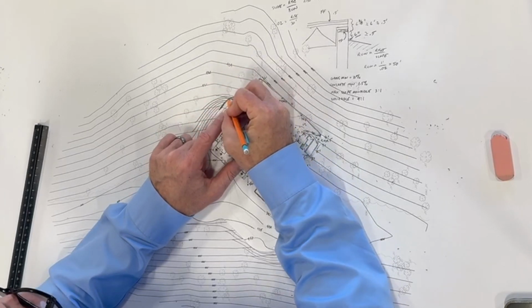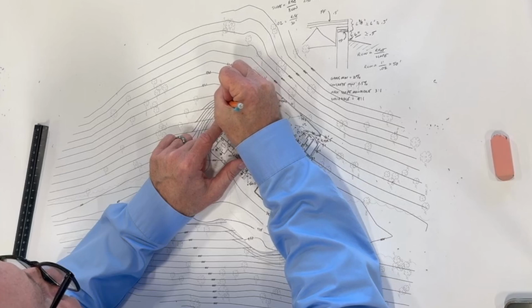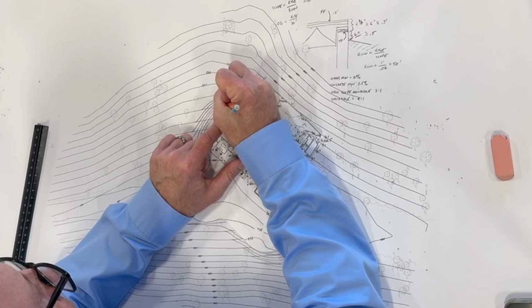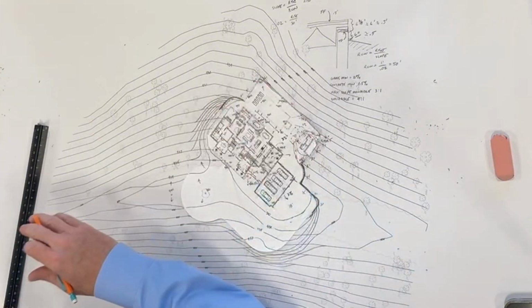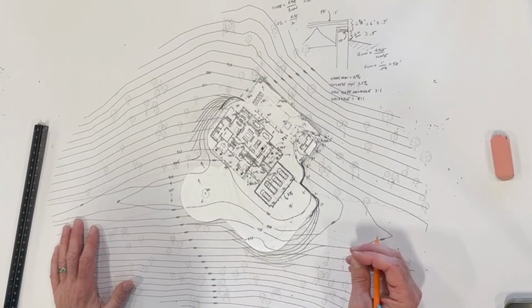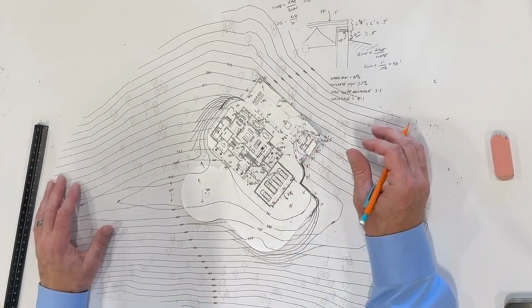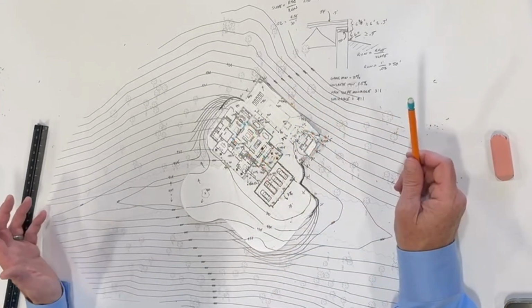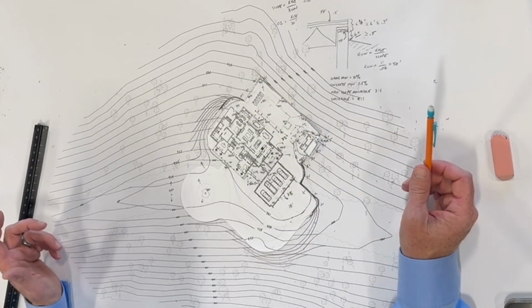And again, I'm looking at where the contour is down below to determine how high this is, right? So whenever the next contour hits is when it drops. 5 foot, 4 foot, 3 foot, 2 foot. So not bad, and it'll just blend into nothing, right? So, all right. Now, yeah, so I think basically that works. This is where maybe we price out the retaining wall to determine if it makes sense or not.